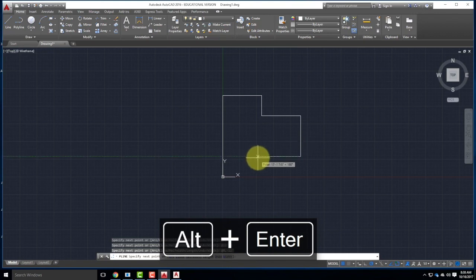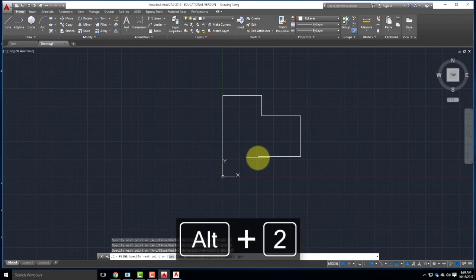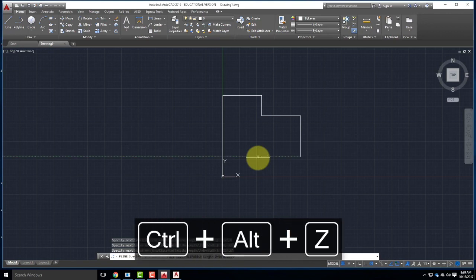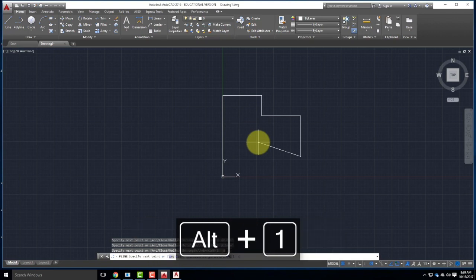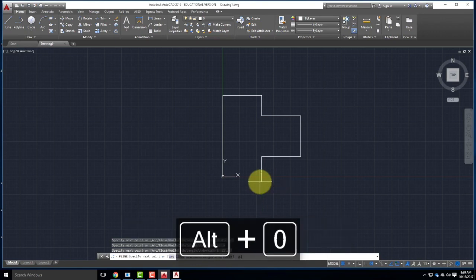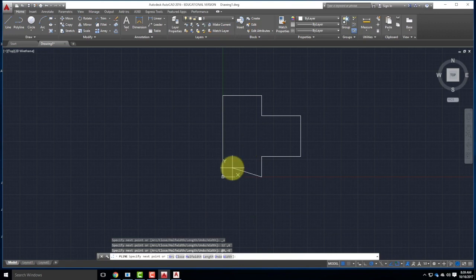You get the difference. The at sign is that relative. I could flip back for illustration purposes. This one would be at 12 feet, comma, 6 feet. Oops. I shouldn't have put the at sign in. This is just 12 feet, comma, 6 feet. There we go. Or I could say at 0, comma, negative 6 feet. So you can flip back and forth between the two. It's just whether you put the at sign in or not. When I'm done, I can snap back to where I started.